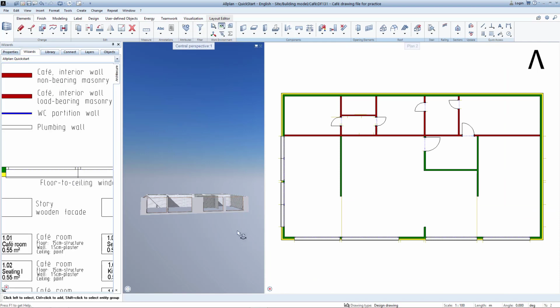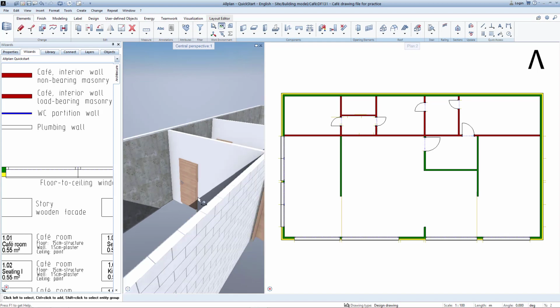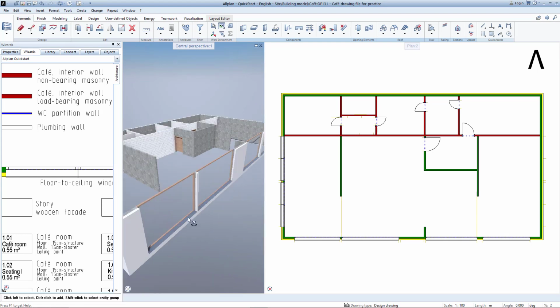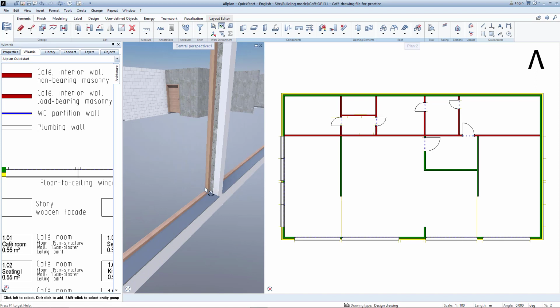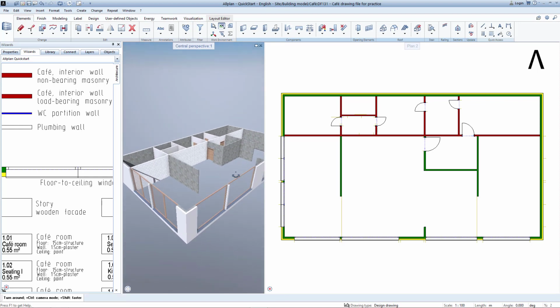And just like with the doors and how the door smart part was created in one go very simply next to the actual door opening, it's also the case here with the windows. The window openings are created and the window smart parts are directly attached. Why is this? It's quite simple. The architecture smart parts, such as windows, doors, and many other parts, are sub-objects of the respective opening. If you double-click with the right mouse key on the existing door or window opening, and this already contains a smart part as a sub-object, then this will also be created right away without any additional effort.